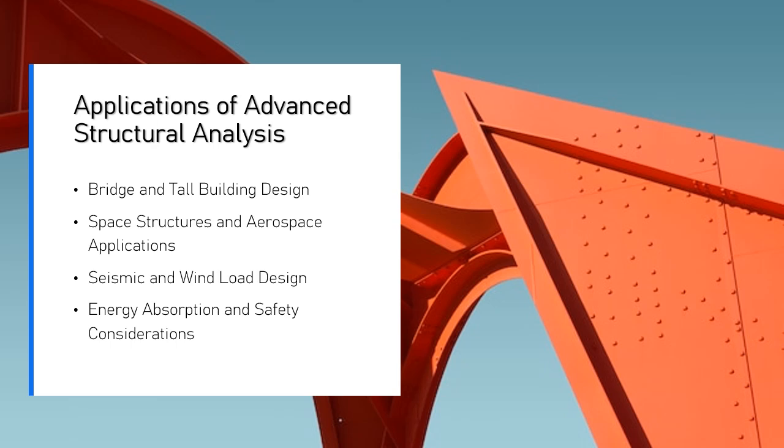1. Seismic dampers and energy dissipation systems. Case study. Use of dampers in high-rise buildings, e.g. Taipei 101, Taiwan. Challenges. Tall buildings like Taipei 101 in a seismic zone face challenges related to wind and earthquake loads. The building's slenderness ratio makes it more susceptible to dynamic motion caused by seismic forces.